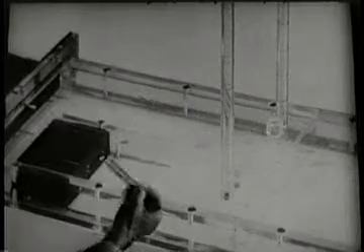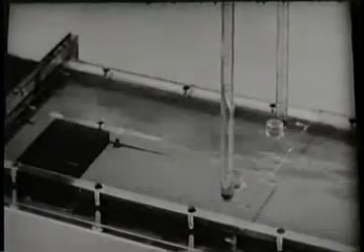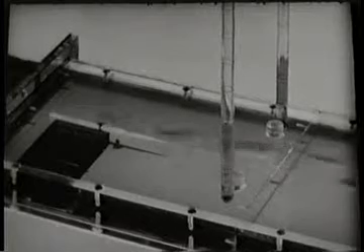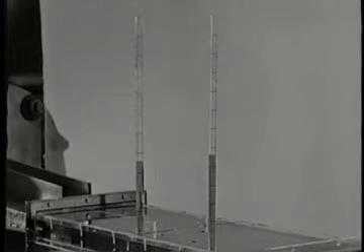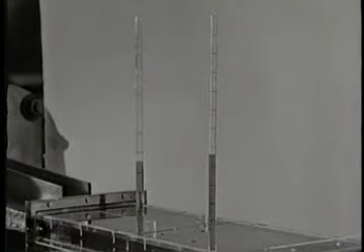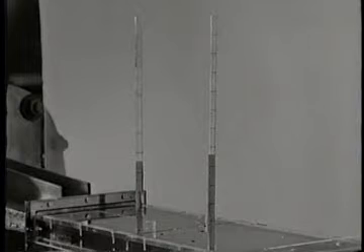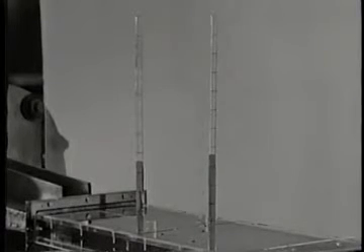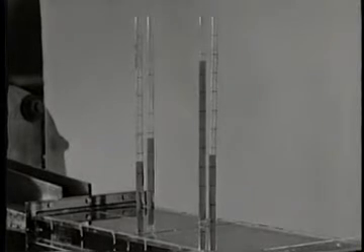The static pressures shown by these two manometers are equal. If you used Bernoulli's integral, you might conclude that the velocities of the two streams are also equal. Let's see. These are stagnation pressures, read by pitot tubes. From the two dynamic pressures, we see that the velocity downstream of the obstructed passage is less than for the clear passage.